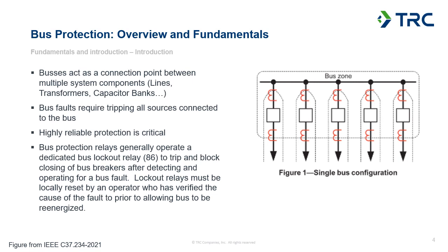So it's very critical that our protection operates with high reliability, and in many cases, it's very critical that we're operating very fast. So in general, we're trying to apply a bus protection zone that will operate for faults on the bus, and similar to what we talked about with our line protection and other applications, we've got to cover any of the expected fault scenarios that could happen on the bus. So whether that's 3-phase faults, line-to-line faults, line-to-ground faults, different types of equipment failures, the potential for impedance in those faults. So there's a lot of things we have to consider.